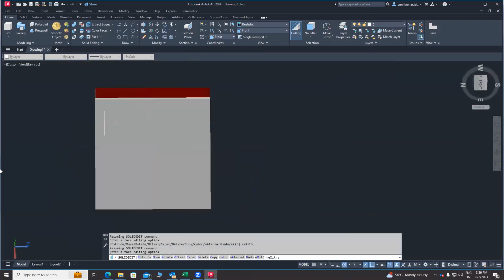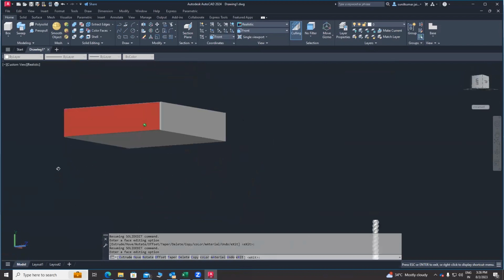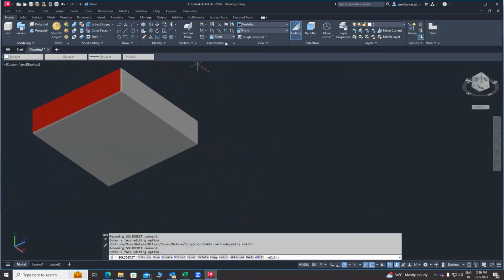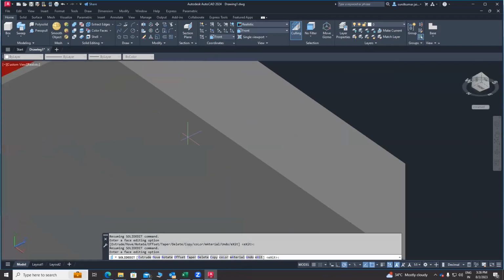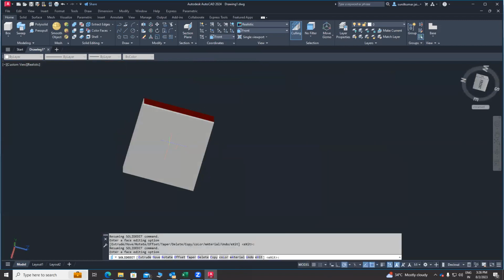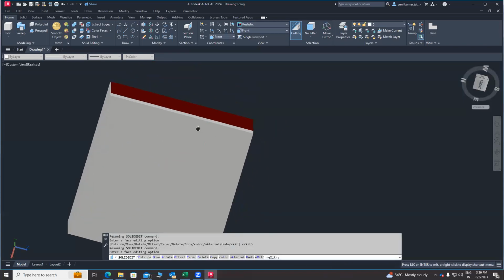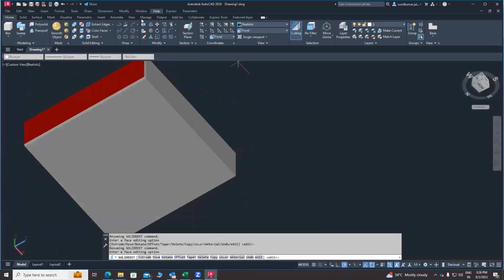Okay, and I'm just showing the concept of the coordinate system, because without understanding the coordinate system concept, we can't design any AutoCAD 3D correctly. So, coordinate, there are a lot of options like 3 points, origin, base VCS. So just click on the 3 points.